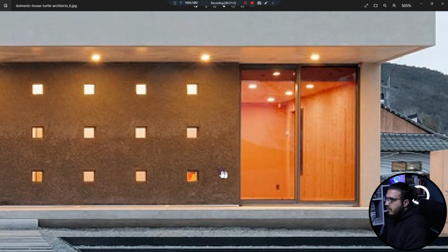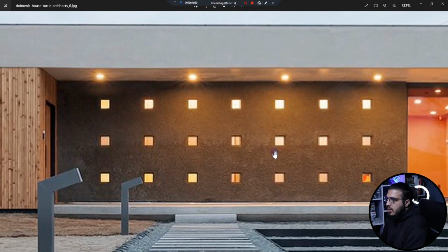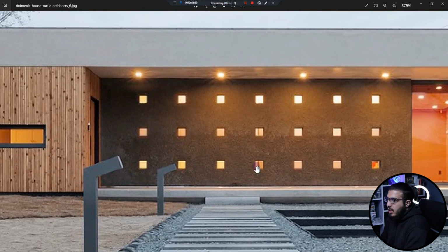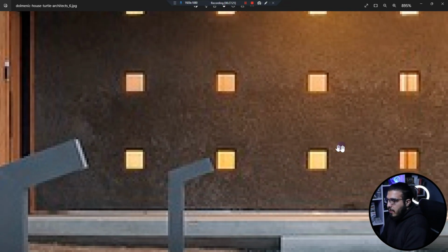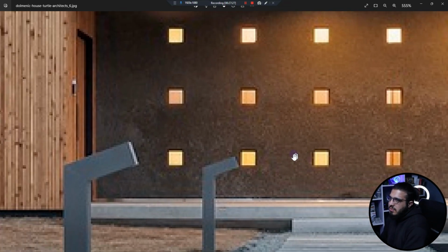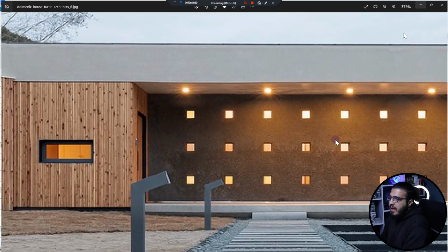Now the next, we have some small windows in here. Because it's a repetitive task, I'm not going to do it right now, but I think the best method is to use curtain walls in here, because these are not windows. You can use windows too, but I think curtain walls are much faster.